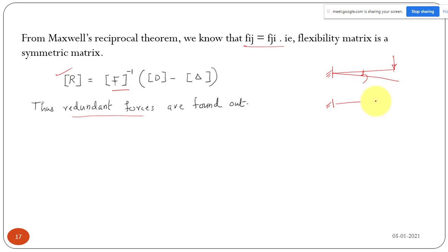That will be equal to applying the load here and finding the deflection here; both will be equal. You are getting what I am saying. The reciprocal theorem is already there in SA1. So apply load 1 here and find the deflection here, that will be equal to applying the load here and finding the deflection here. That is what the reciprocal theorem is saying.